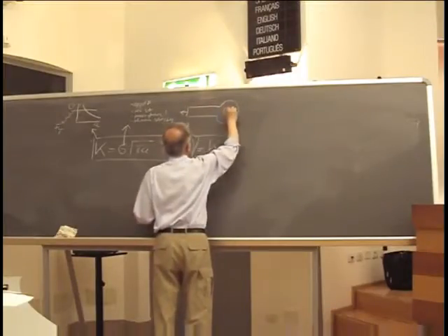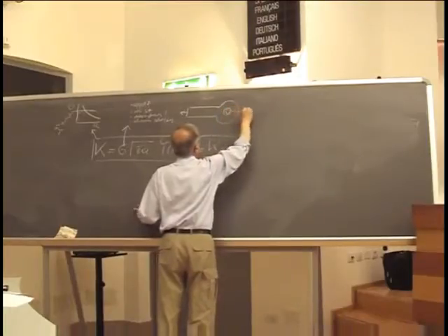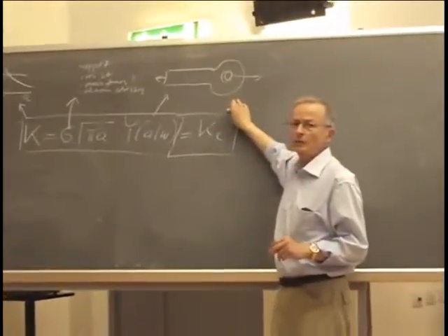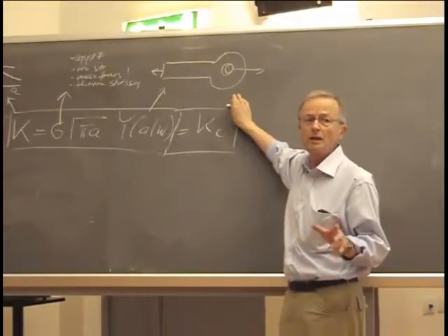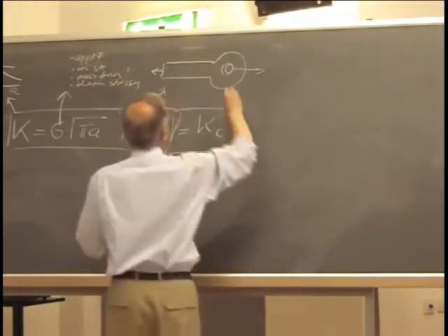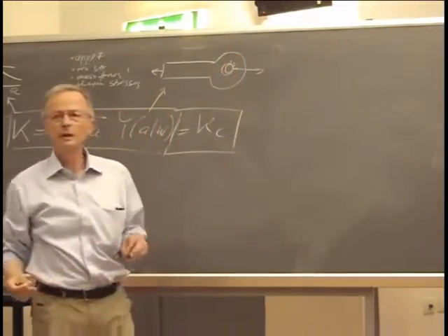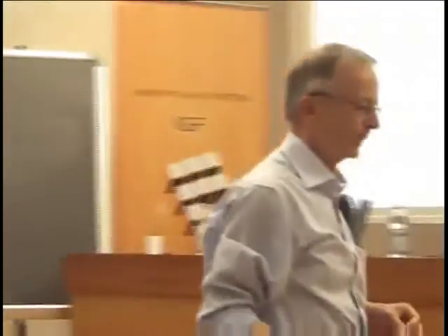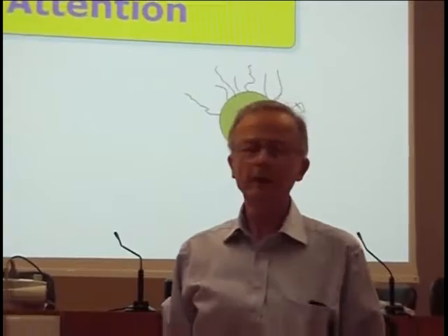So it was loaded this way. The bolt, of course, had a little bit of clearance. And it took a series of experiments to learn where the crack was going to initiate. It could have initiated here, here, here, here, depending on the clearance, most probably also depending on the material pairs. The location has a strong effect on the magnitude of our Y function.